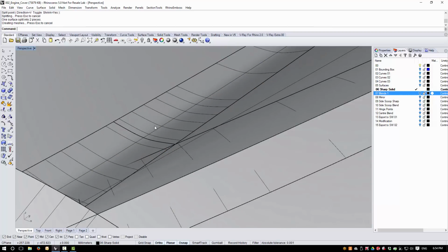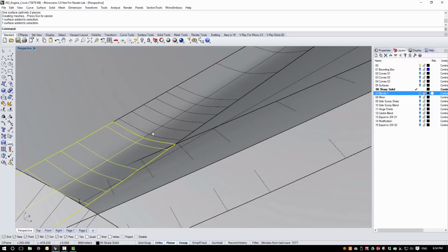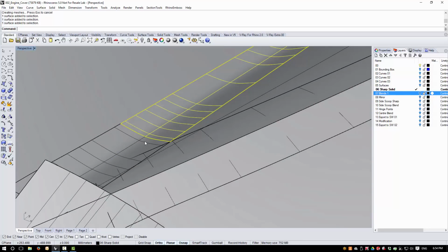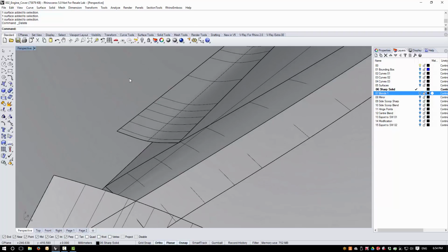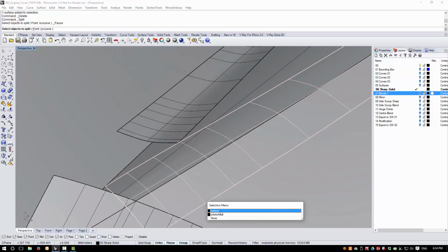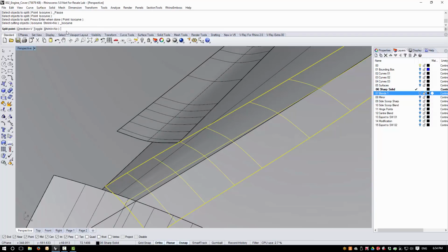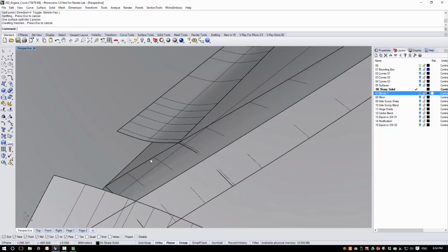When the shrink option is enabled, both of the surfaces that I obtain by splitting will effectively be untrimmed. And this idea of having an untrimmed edge here is very important in case we need to run a match surf command to it. So I'll now repeat the split at isocurve command on the second of the blends here, and I'm going to need to reinstate the shrink option here. This option isn't sticky, so be wary of this. And split again.